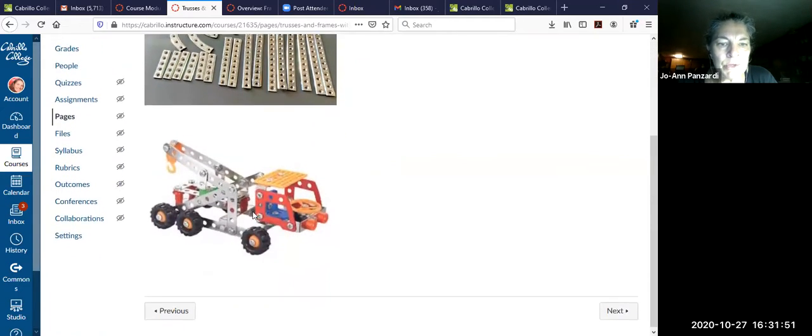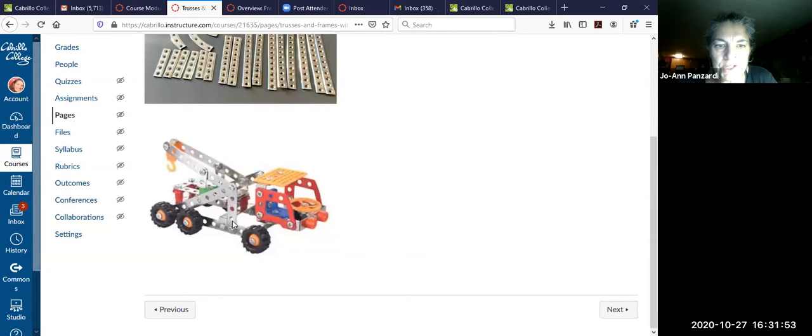So what I'm going to do is show you here. Can you notice this vertical member right here? Everybody can see it? It has 1, 2, 3, 4, 5 holes. Notice it's only connected on the end, right? And it's only connected on this end. This is called a two-force member because it only has forces on the end. And we don't see any forces on the end, but we know it's a connection, which means the reactions it supports are on the end.